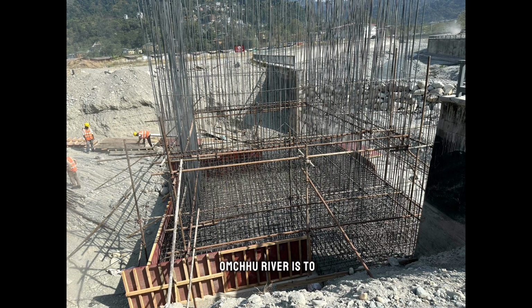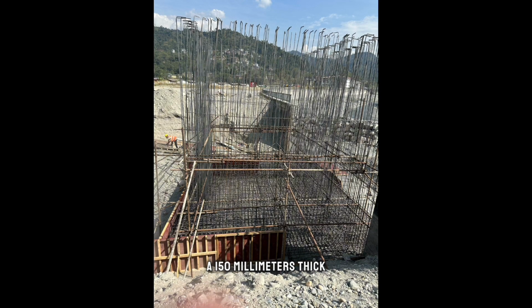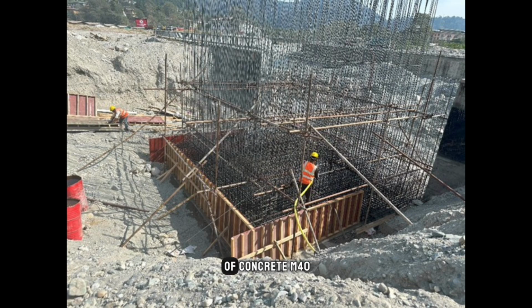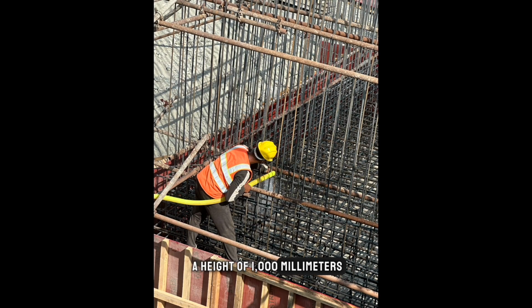The bridge over the Phuentsholing River is to be designed and built as a traditional Bhutanese timber bridge. Before the foundation is laid out, a 150 mm thick compacted stone soling and 100 mm thick leveling concrete is poured to level the surface with the pre-existing reinforced concrete diaphragm wall, after which the foundation of concrete M40 is poured up to a height of 1,000 mm.